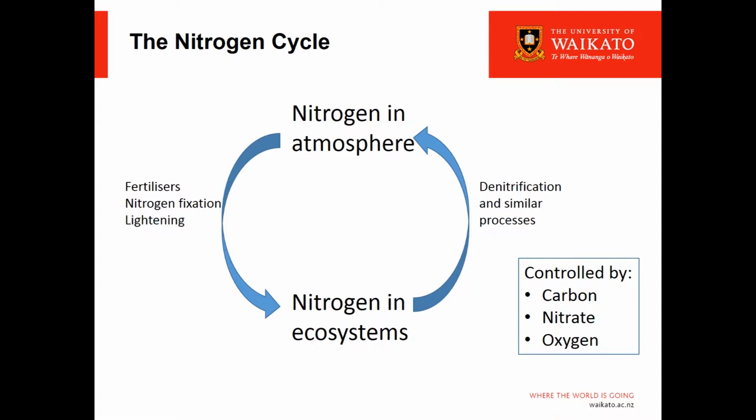Carbon is the energy source, right? Same as us, we have food. They need some sort of carbon support for energy. They need nitrate, that's their equivalent of what we have with oxygen, so they use nitrate instead of oxygen. And they need an absence of oxygen because they would prefer to use oxygen rather than nitrate. So if oxygen's around, they start using oxygen and they don't touch the nitrate anymore. So you need a carbon source, you need the nitrate, and you need an absence of oxygen.